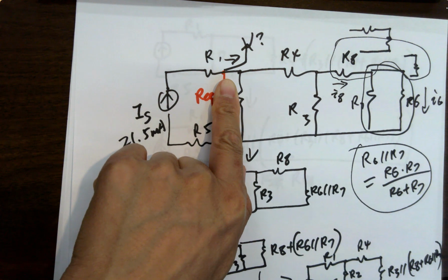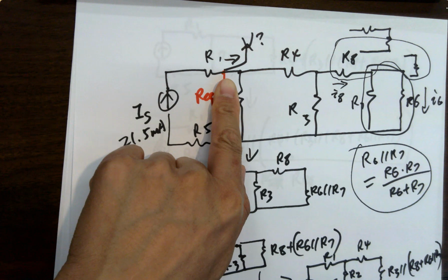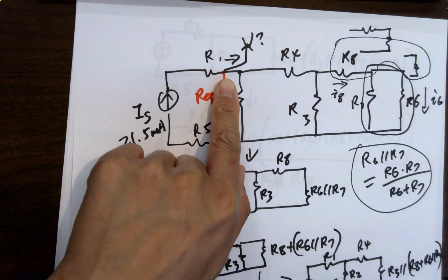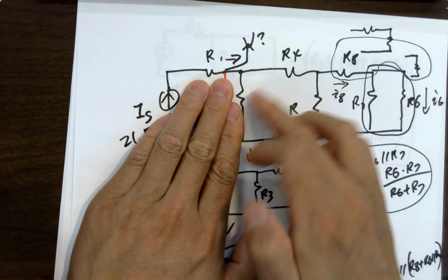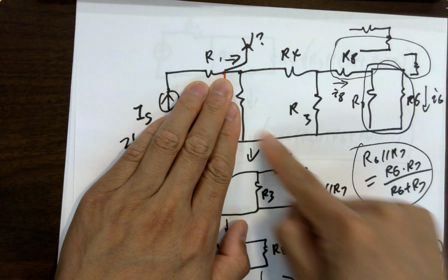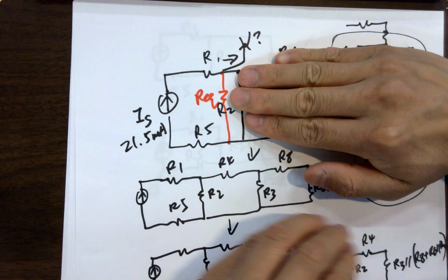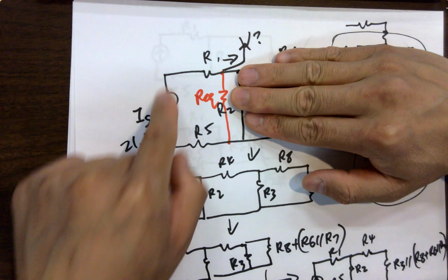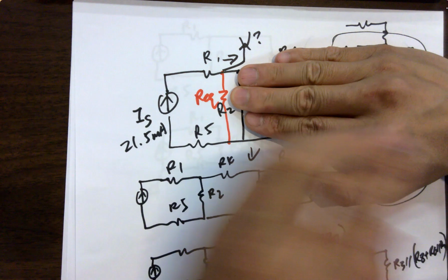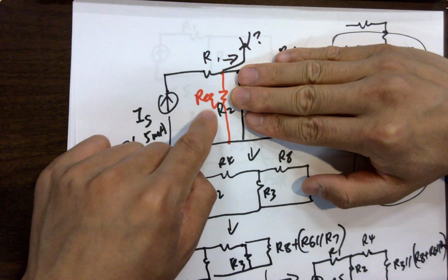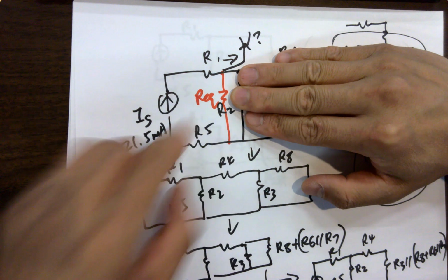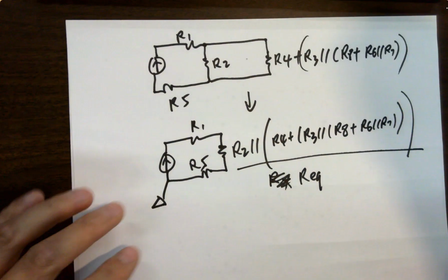Do they have the same voltage? Think about it one more time. So I either have all the original resistors in the circuit, or I converted everything to this equivalent resistor, just 3 resistors in the circuit instead of a lot of other ones. But I use the equivalent resistor, and then let's see how to calculate the voltage first before we move forward.